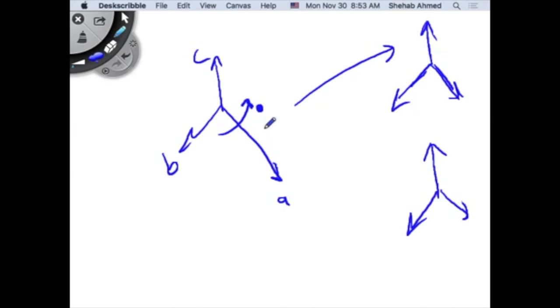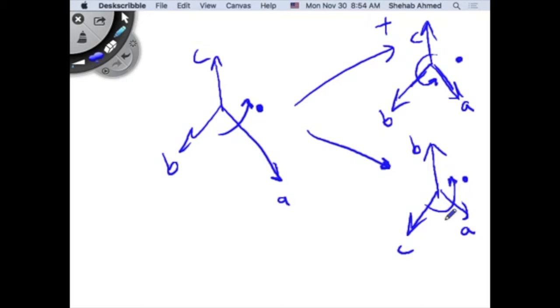So what symmetrical components theory tells me is that I can take this unbalanced system and chop it up into a positive sequence supply, meaning this is A, this is B, and this is C, rotating this way for an observer standing here. A, B, and C, right? And for an observer standing here, A, C, B. So for an observer standing here, I will now see something different. I will see phase A, then phase C, then phase B, right?